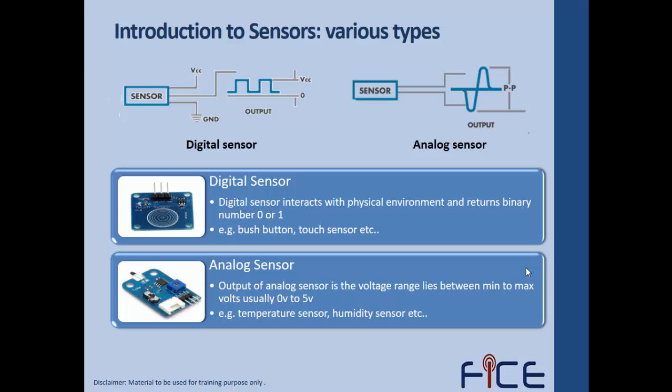Digital sensors are modern successors of the analog sensors. In digital sensors, the signal measured is directly converted into a digital signal output. Examples are touch sensor, digital vibration sensors. Whereas an analog sensor produces a continuous analog output signal, and this continuous output signal produced by the analog sensor is proportional to the measurand. Examples are accelerometers, ambient light sensors, temperature sensors.